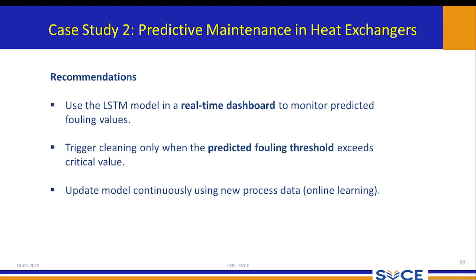So the recommendation goes like this: use the long short-term memory model in a real-time dashboard to monitor the predicted fouling values, trigger cleaning only when the predicted fouling exceeds the critical threshold value, and update the model continuously using new process data, that is, online learning.